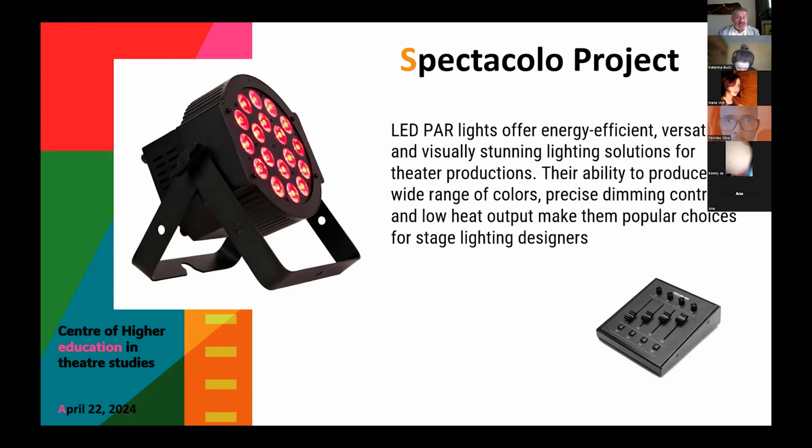LED par lights generate less heat compared to traditional incandescent or halogen lamps, but they still require effective heat management to ensure optimal performance and longevity. LED par fixtures often incorporate heat sinks or fans to dissipate heat and maintain safe operating temperatures, especially if it's big, with many watts, I mean.